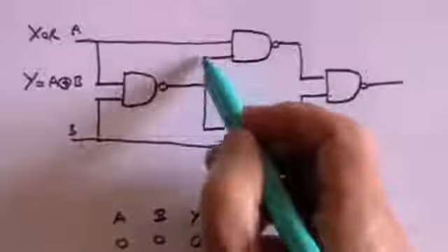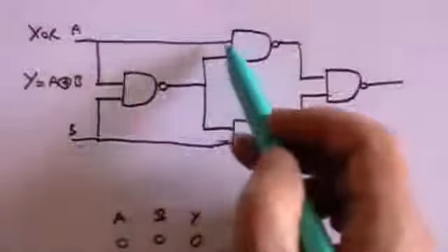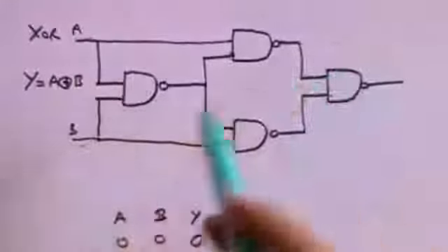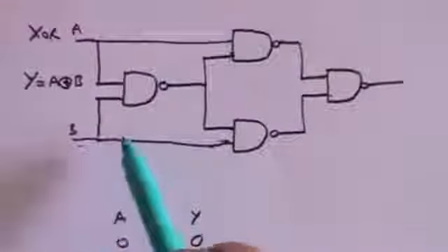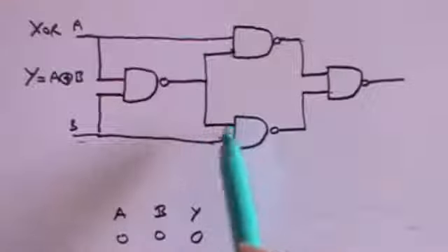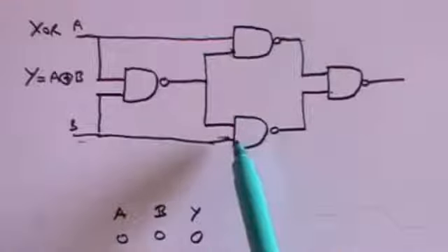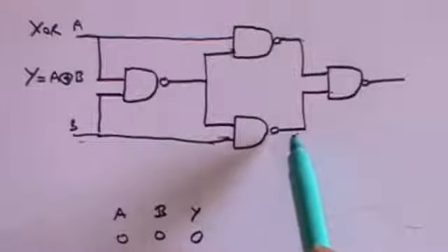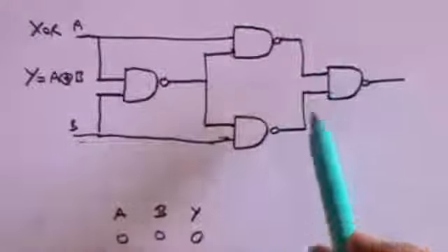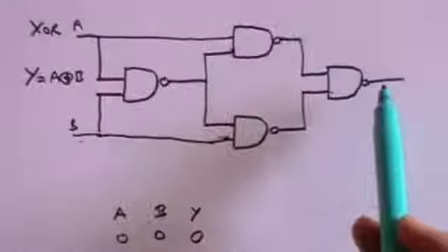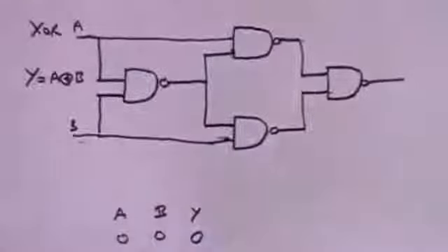A positive out coming in here together with a 0 will give you a positive out. So that's a positive coming in here. What about at this end? Well, B we said, remember, is positive. So B is positive. The output from here is positive. So we've now got 2 positives going in. That means you're going to get a 0 coming out. You had a positive coming in here, a 0 going in here, a positive and a 0 will give you a positive output.